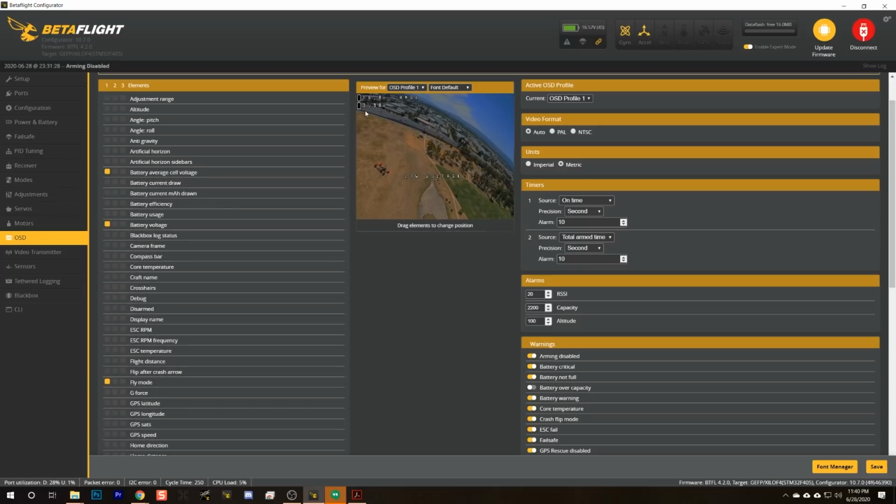So I need to stop flying when that average cell voltage gets down to about 3.6 to 3.7. If it goes below 3.0, the battery is being irreversibly damaged, and somewhere between about 3.5 and 3.0, it just drops off a cliff. So don't think that stopping at 3.6, you're like, well, could I fly longer? No. Once you get to about 3.5, it just goes, bleh. So stop around 3.6 or 3.7.